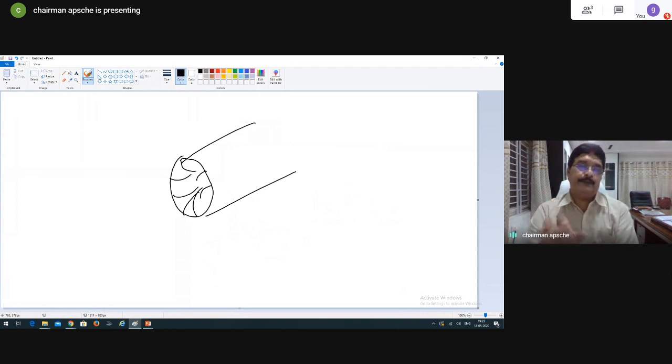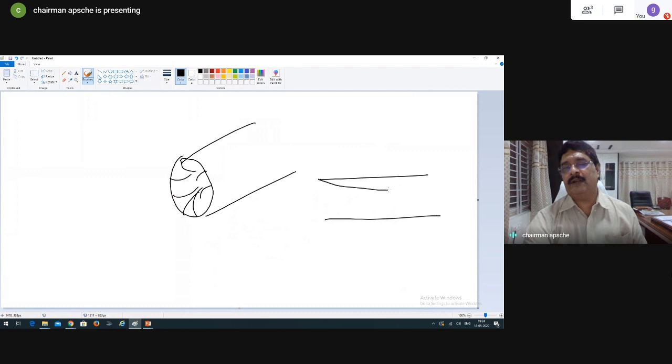There will be zero, and slowly it starts increasing in the boundary layer. So all around 360 degrees it happens. But when I take a two-dimensional view of this, one boundary layer is forming here, another boundary layer is forming here. Somewhere, if you go to a greater distance, these boundary layers will intersect.